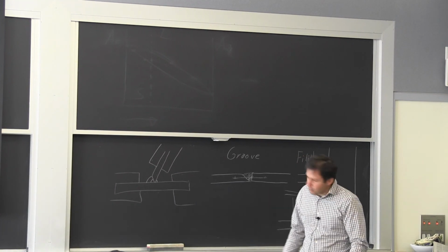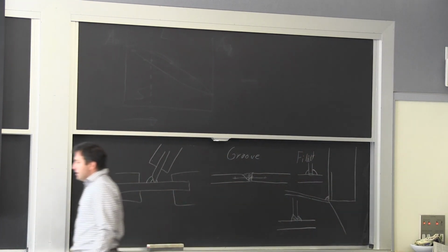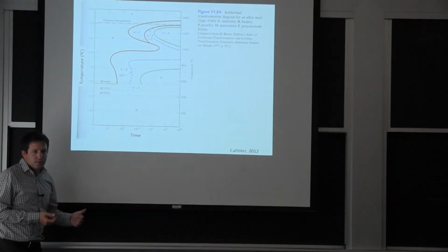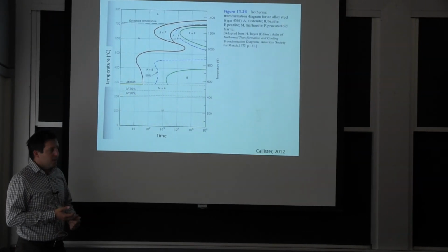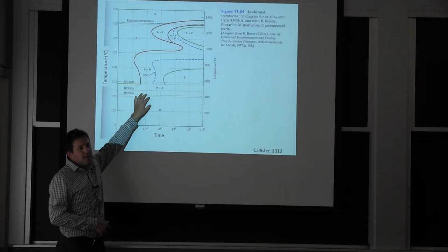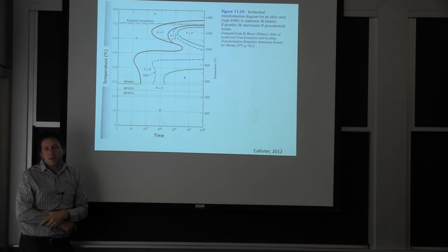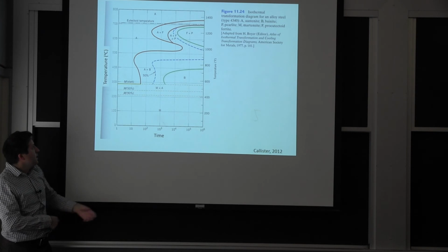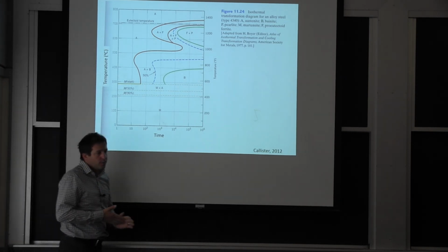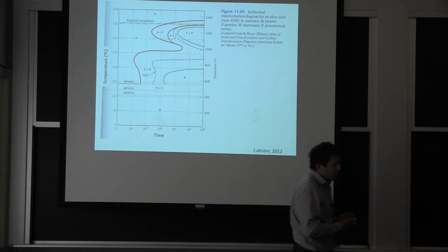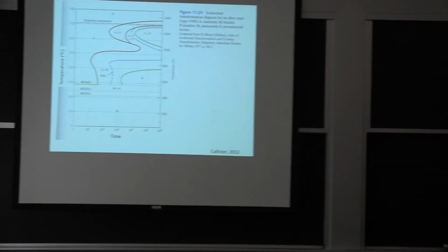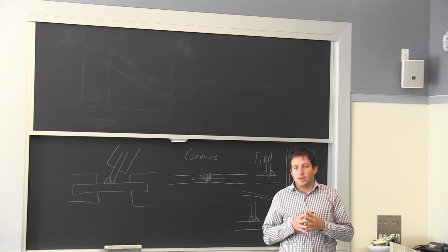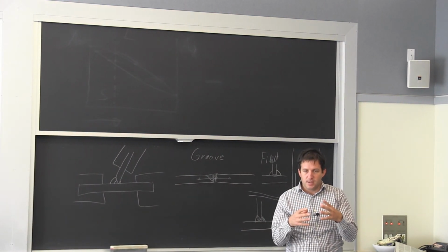The biggest advantage to this is you minimize the amount of residual stresses or even the risk of distortion cracking, and you can start forming that martensite that we've been talking about yesterday. You form the martensite, and then you can heat it back up for the tempering treatment. Now, I didn't talk too much about the tempering treatment, but it is effectively like precipitation hardening. So we have that martensite, it's very unstable.